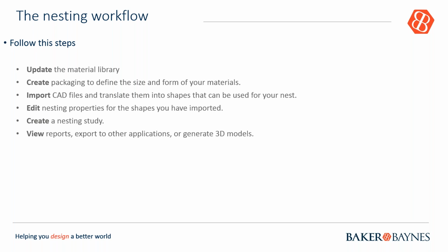The create side of it, the import. CAD files are translated into shapes. You can bring in any CAD, so it supports any CAD. If you've got files that are not IPT or IAM, if they're coming in as a step, you can import them into Inventor, and from there you could take them into the nesting environment to create the study.